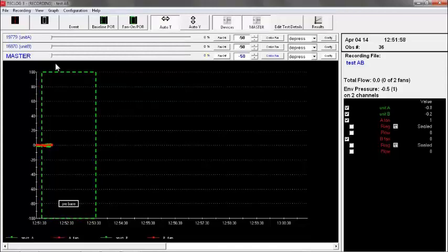And you can see we have 3 fan controllers here, and 3 cruise targets. We're not going to use the master. The master is for if you're controlling both fans with 1 bar, but if we did that and they're both brought up to equal rates, we'd have different pressures in each unit unless they're exactly the same tightness.